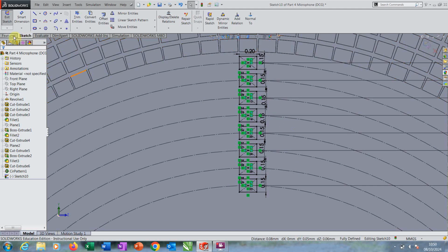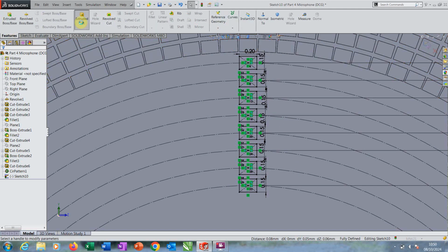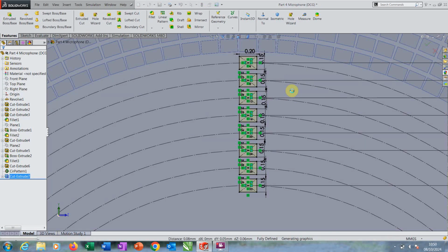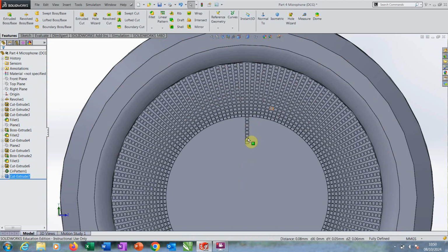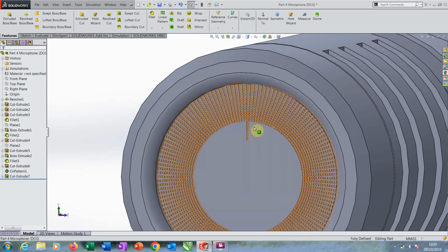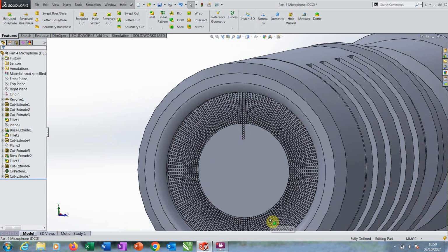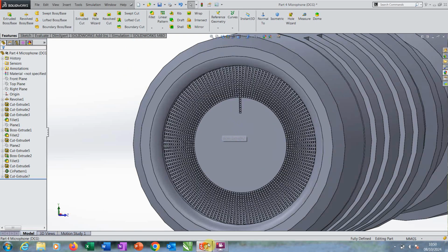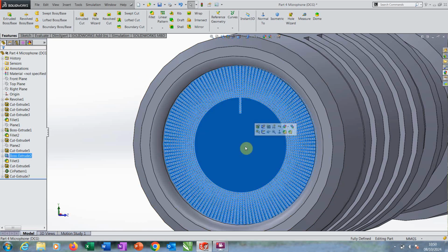and as we've done before, features, extruded cut, 0.1, it remembers it. Press click. So the cuts aren't too bad. It's when it goes to pattern because there's so many instances going around. So lads, I'm going to have to pause the video again, but I'm just going to bring you through it, so just make sure to go back here.